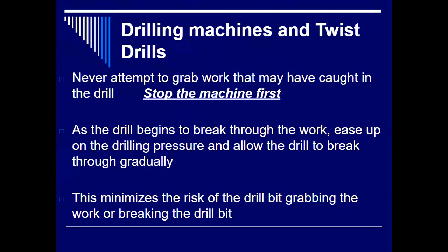So never attempt to grab work that may have caught in the drill. Sometimes it'll pop out of the vise and it'll be sitting there spinning away. Don't try and grab that work. Hit the stop button, step back, get out of the way. If that goes flying, you don't want it to hit you.